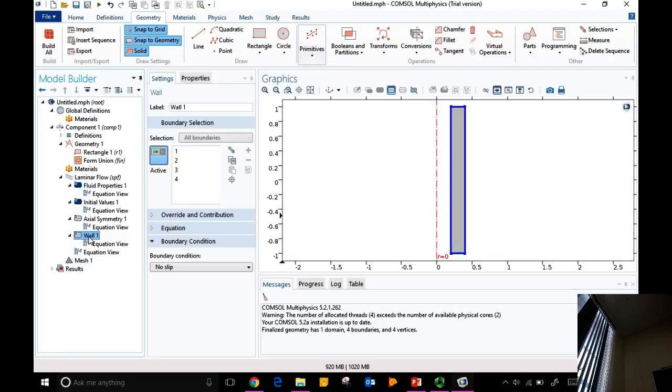If I go and say solve right now, what did it give you? 0 everywhere. It will satisfy that, right? All the boundaries are 0. The fluid initially at 0. And the Navier-Stokes equation, left-hand side, right-hand side, everything is 0. It is satisfied. 0 is a valid solution to the Navier-Stokes equation, but there is no forcing. So it is the forcing that causes the flow. Forcing from the boundary or forcing as a body force, the rho g term. Okay? But rho g term in incompressible flow is tricky because if it is hydrostatically balanced, then there is no flow arising out of it.